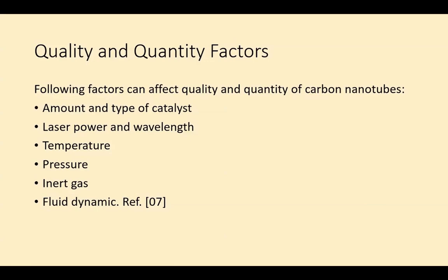Then a black powdery substance moves from the high temperature zone to a water cooled copper collector positioned downstream just outside the furnace. Then the nanotubes will gather from the soot and stick to the walls of the flow tube. Carbon nanotubes produced by this method are purer, almost 99% purer than carbon nanotubes produced by the arc discharge method, and those have a very narrow diameter, about 1 to 1.6 nanometers for single wall carbon nanotubes.